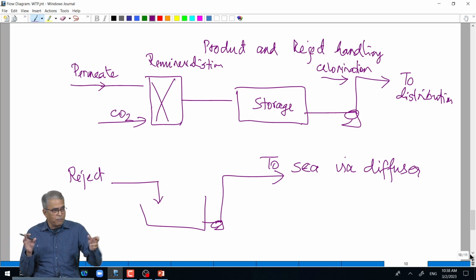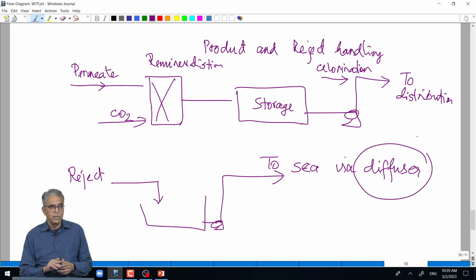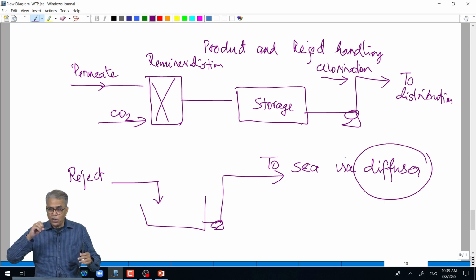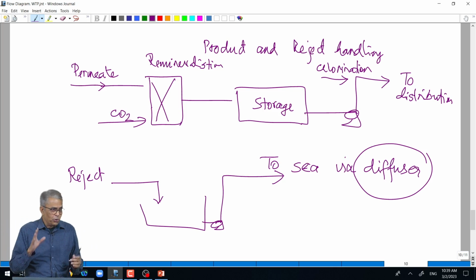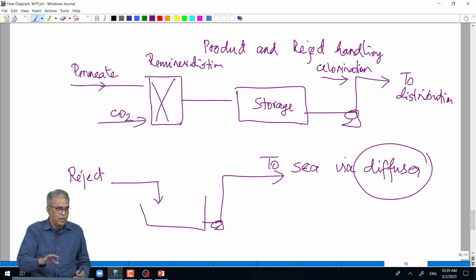Do some study, find a place and put it there, through something called a diffuser, which is a final end pipe that does not discharge at one point but spreads the discharge out, and put the whole thing into the sea. Our fellows are standing there asking to bury it, please, but a diffuser cannot be buried, by the way. The pipeline can be buried, with permission, and there is a special cage made for the diffuser, and it is put out.